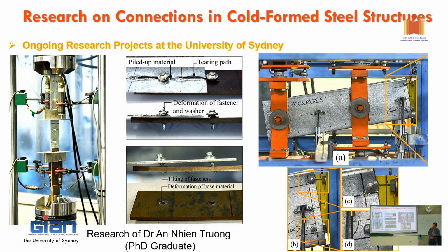The reason I ask is that I have come across projects where there is a need to put one floor above, especially people in Delhi like to have one floor above, which is light, and then you don't have to change the foundation. But the biggest problem there is that it has to be properly anchored.